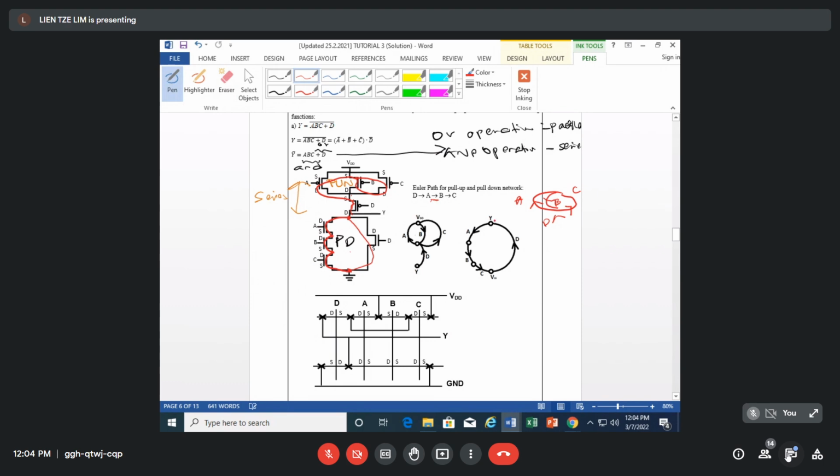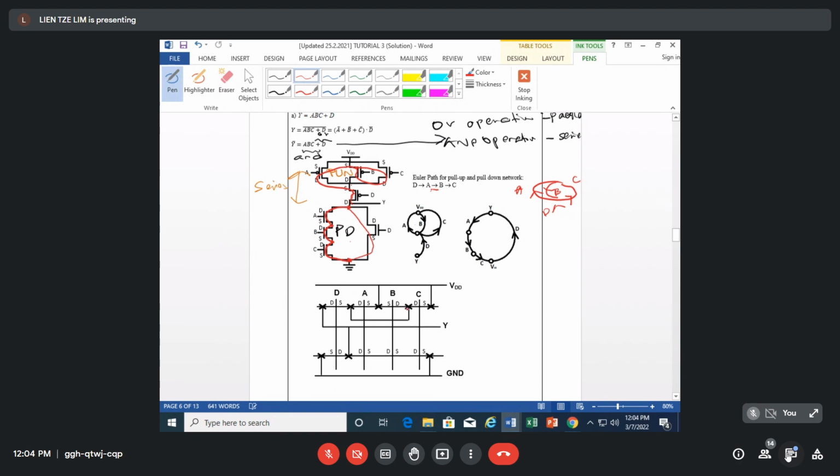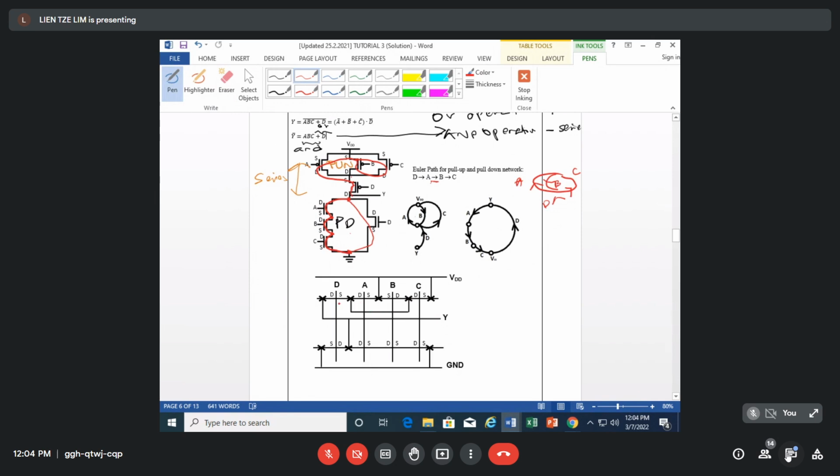After we determine the Euler path, we can start to draw the stick diagram. So this is the stick diagram, with the order based on the Euler path of D, A, B, C. Now we should label the drain and the source terminals. We need to label them so that we can draw all the connections correctly.